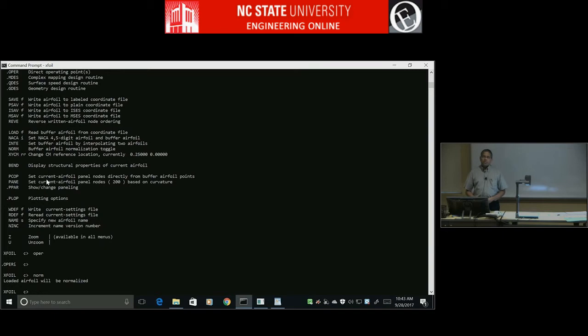let's say you're putting coordinates in from an actual model. So you have a wind tunnel model or something and you take it to some digitizing machine and they use a digitizer to digitize all the coordinates and you put that into Xfoil. That airfoil may not be exactly horizontal, right? It might be at some angle and the length might be some weird units.